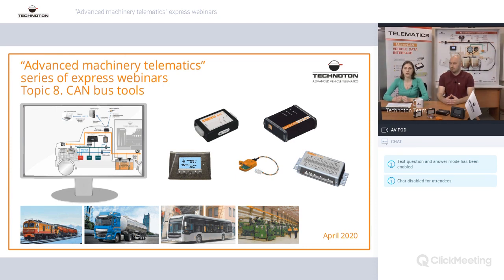I will mention further what kind of parameters are available in the CAN bus. MasterCAN SAE J1939 and 485: input is CAN, but the output interface is already 232, 485, and Modbus is also available. MasterCAN VGate: input is CAN, output is J1708 or RS-232. Modbus is also available.